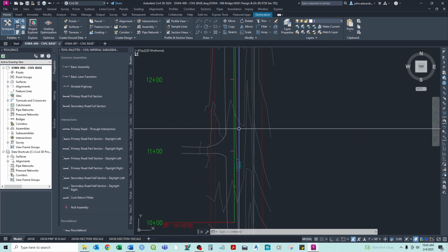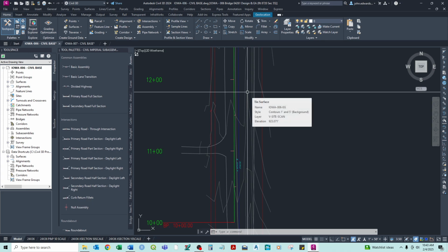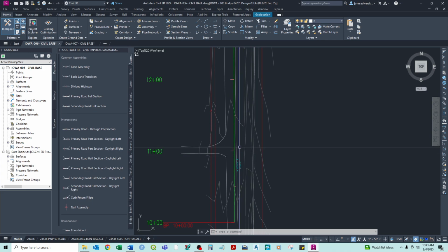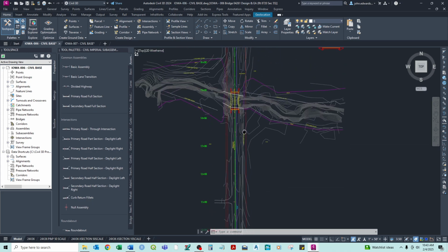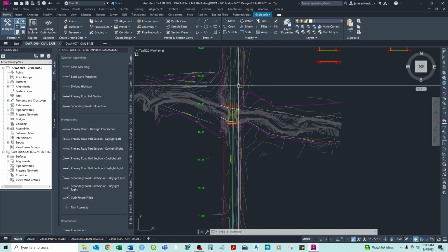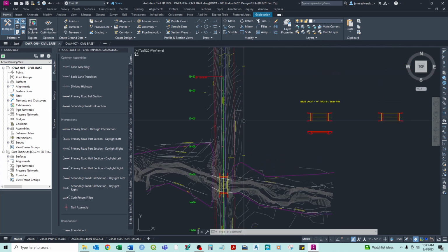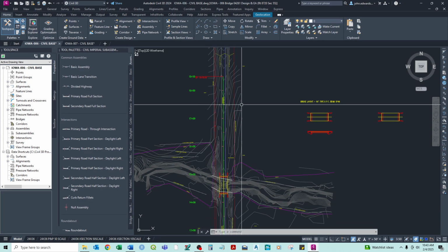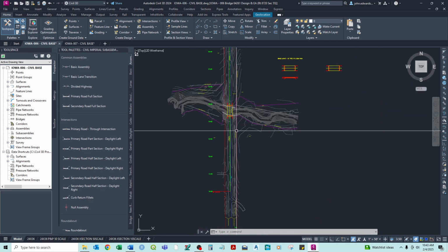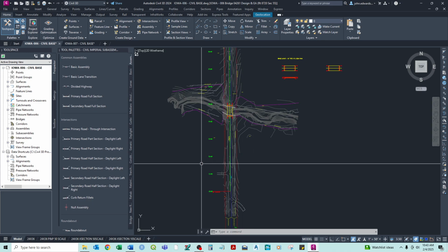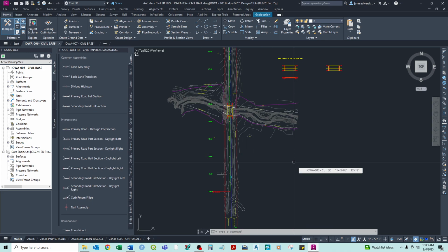This is just a narrow, I think about 18-foot wide gravel road. Right now actually it's dirt. We're just going to be laying gravel, a 6-inch gravel base, and we're going to put probably two 9 or 10-foot lanes with a couple foot shoulder, so we'll just gravel across the whole width.